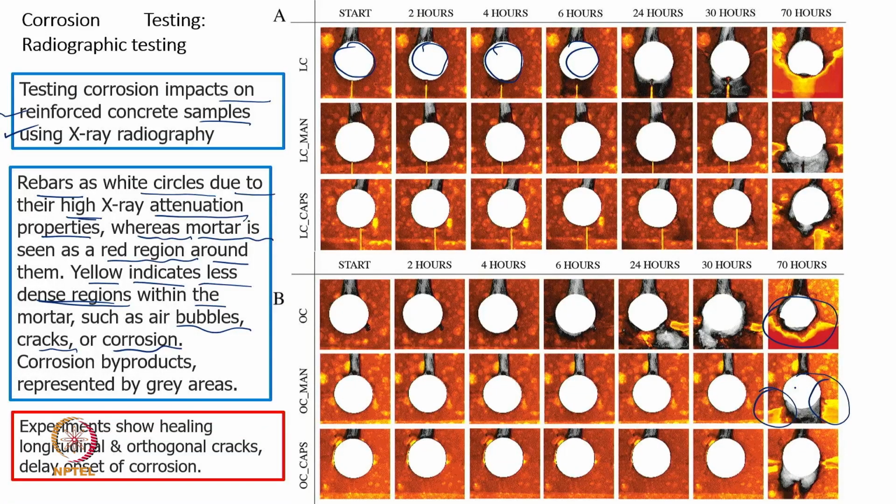In this case you are able to see more and more yellow color on the surface. Even though what we see with the naked eye may contradict it, we should believe the radiography results if we want a long life. And after 70 hours we are able to see more and more cracks in the surface that will lead to failure.